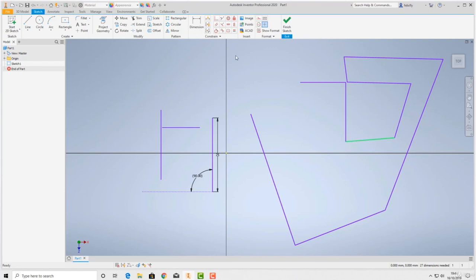So if I click perpendicular, I can select two lines and they're right angles. In this case, we could have just done horizontal, but maybe here we wanted this to be a right angle, but keep this line at that angle there. Okay, so by choosing perpendicular, selecting this line and then that one.